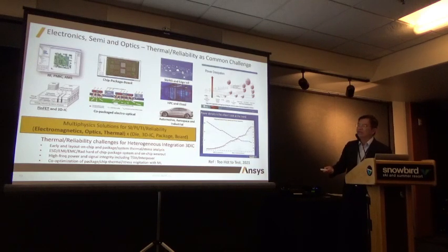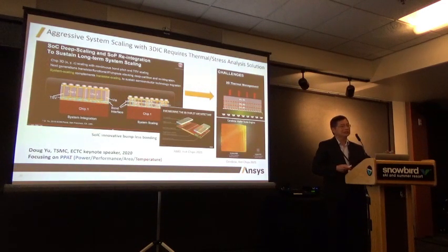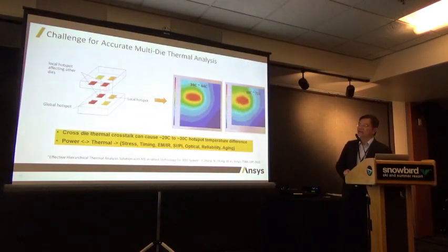That's why there are several challenges, as I mentioned. One of the most important upcoming challenges for 3D IC is temperature. If you look at SoIC on top of the CoWoS design, the SoIC can easily have more than 20 chips, 30 chips in the design. This is an AMD design with V-cache memory on top of the GPU using the SoIC design. Temperature, according to a lot of customers, is a major concern that we need to consider. So that's one of the challenges.